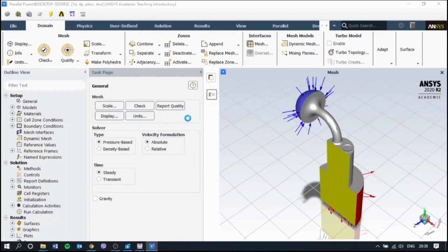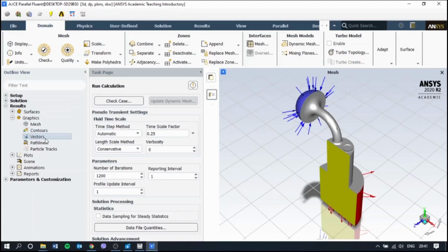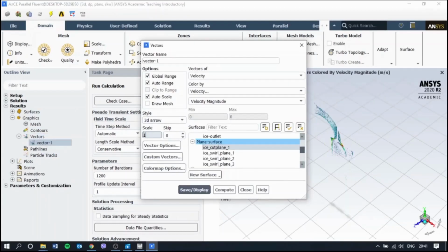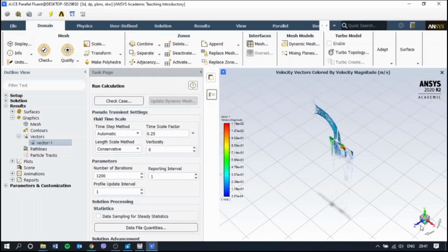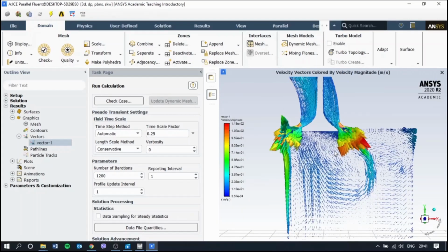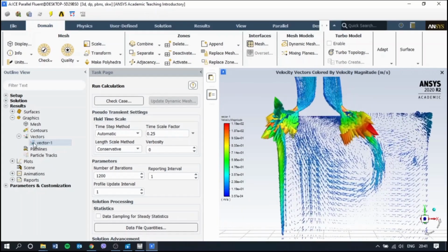Further analysis of the results are completed in Fluent itself by creating vectors. In this case, a specified vector analysis for velocity magnitude with altered scale is being produced on the cut plane. This displays the infamous tumble motion as the circular motions within the cylinder.